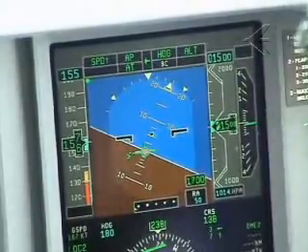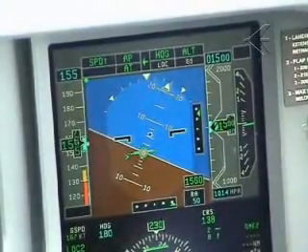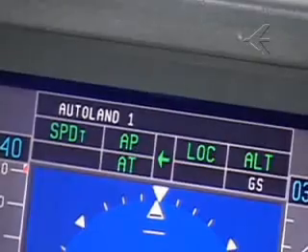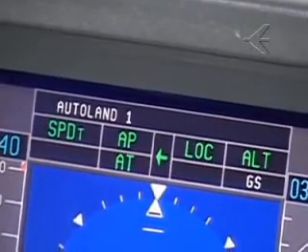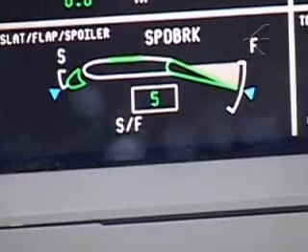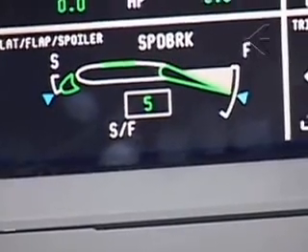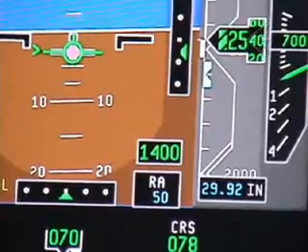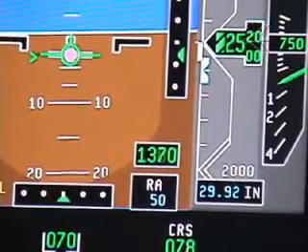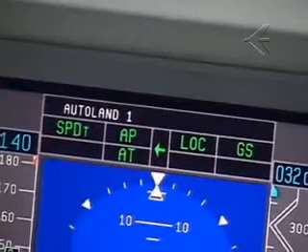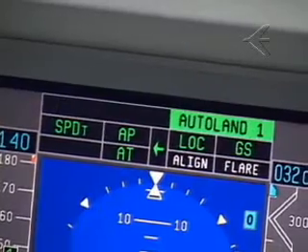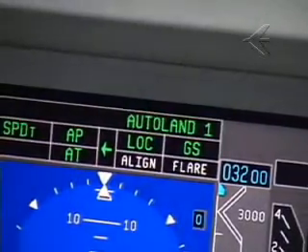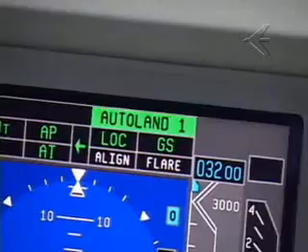When Autoland is armed, that is, all of the previous conditions satisfied, the FMA will show a white Autoland annunciation. To engage the Autoland mode, flaps must be at 5 and both radio altimeters indicating less than 1500 feet and greater than 800 feet. Once both conditions are satisfied, the Autoland annunciation will change from white to green.